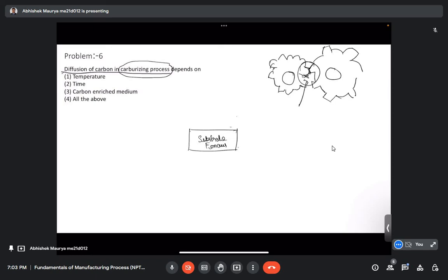component. So in order to avoid this, the surface properties of the gears are improved by improving the hardness, by the carburizing process, or sometimes the nitriding process is also used, improving hardness. And if you improve the hardness, then the wear process will become slower and the component life will become larger.